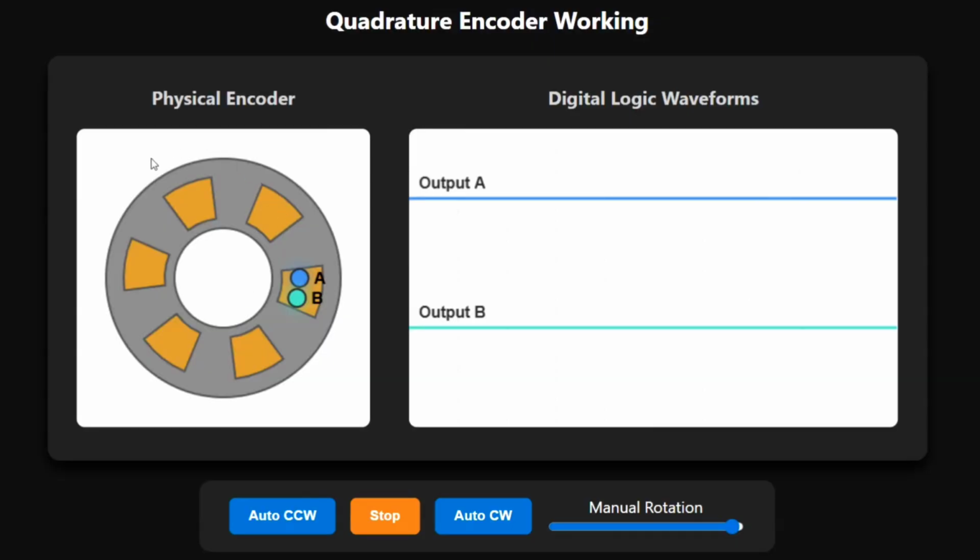So this is the internal structure of the rotary encoder, and here you can see that there are two pins, A and B, corresponding to CLK and DT respectively. These orange patches are nothing but the common pin C, which is attached to the knob of the encoder. Whenever pins A and B make contact with pin C, they output a high signal, and whenever they leave contact with pin C, they output a low signal. Let me show you the simulation.